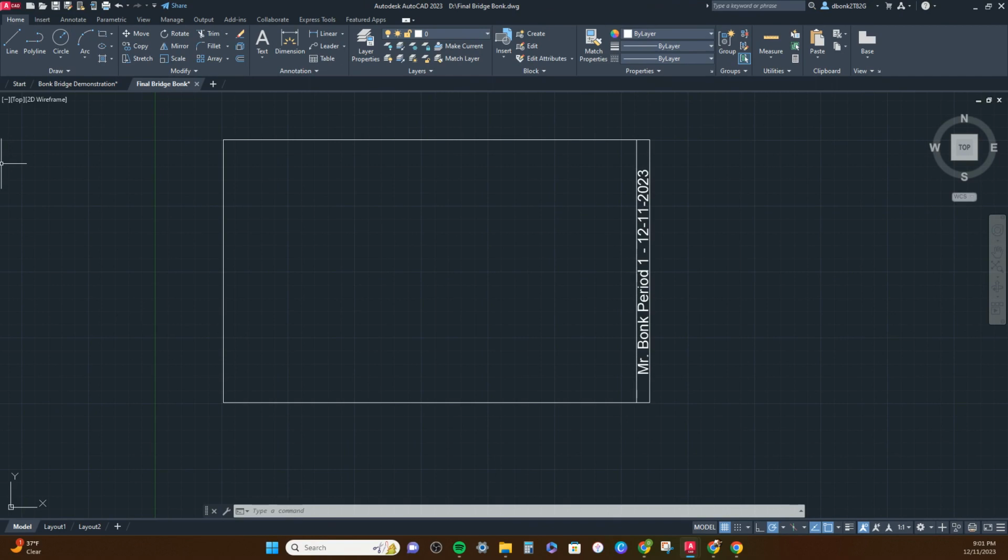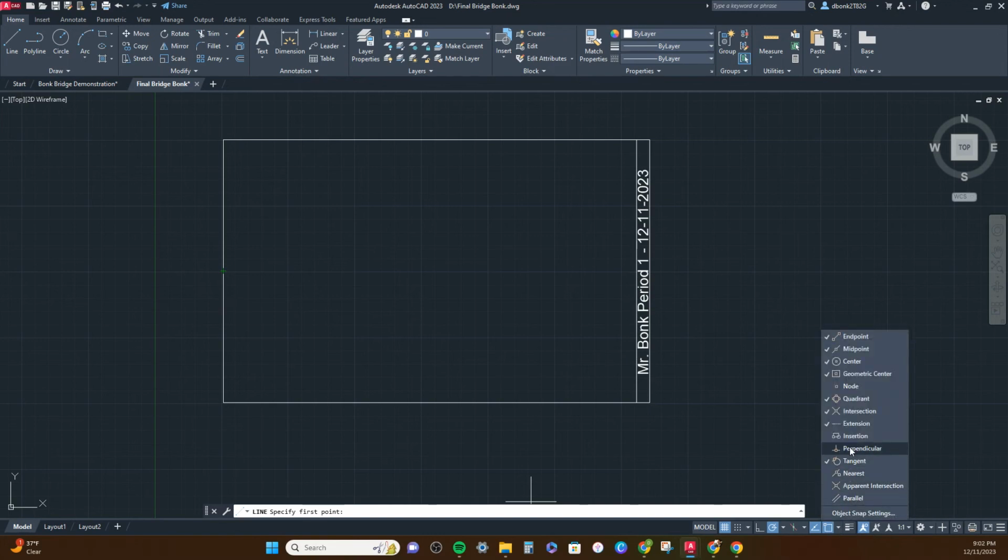All right. So the next step here is to split this in half. This is where you've got to make sure, especially if you're not a student of mine and you just tripped on this video on YouTube, you've got to have all these object snaps on, like midpoint, geometric center. These top four critical quadrant should be on, intersection, extension, tangent, all object snaps that I use.